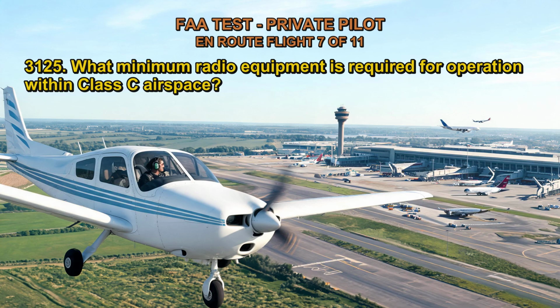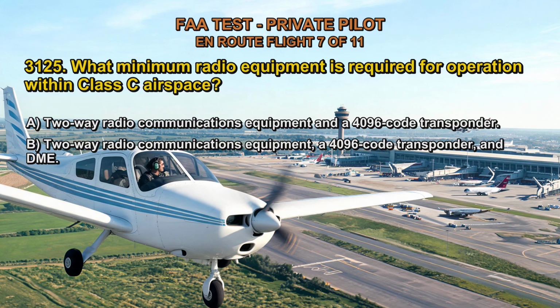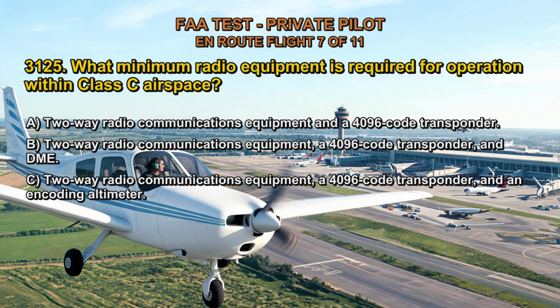3125. What minimum radio equipment is required for operation within Class C airspace? A. Two-way radio communications equipment and a 4096 code transponder. B. Two-way radio communications equipment, a 4096 code transponder, and DME. C. Two-way radio communications equipment, a 4096 code transponder, and an encoding altimeter.